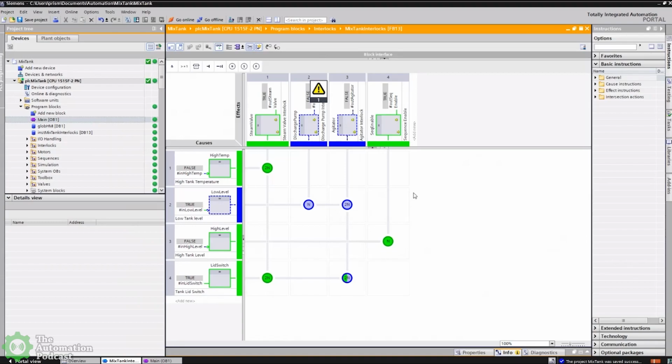And the thought process was, because it is a simpler, more basic logic, it could be applied into applications that aren't traditional PLCs in the field, where a low cost 1200 type PLC would really be cost effective. And then being able to program it with a real simple matrix that anybody not in the industry can completely understand. So it's a significantly powerful tool that's part of the TIA Portal Basic 1200 and scales all the way up. So once you do the block like Ron's done here, you drag and drop it to the library, give it to the team, and that's part of the standard offering.